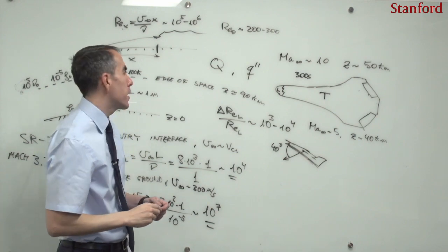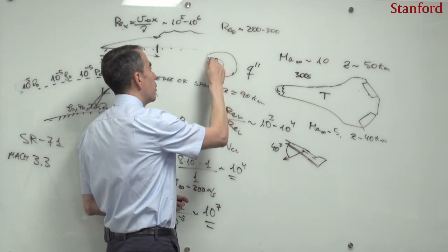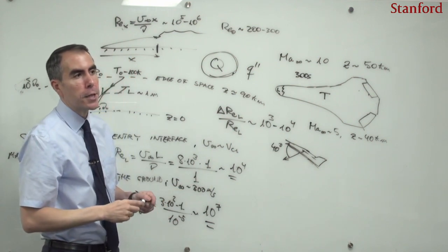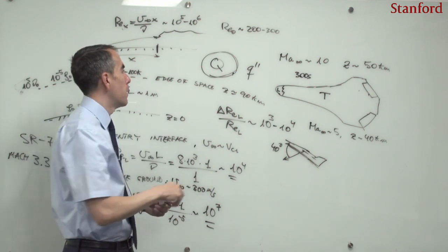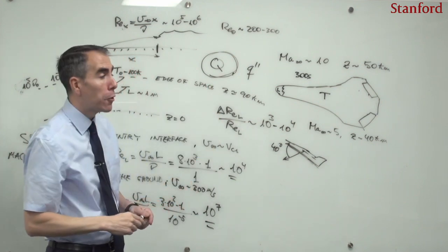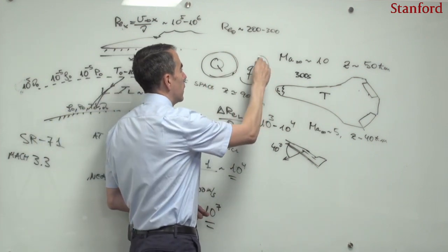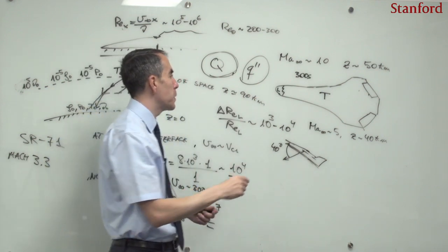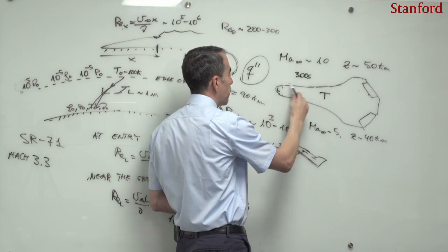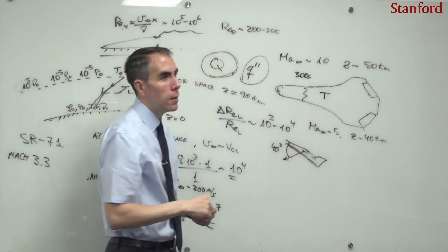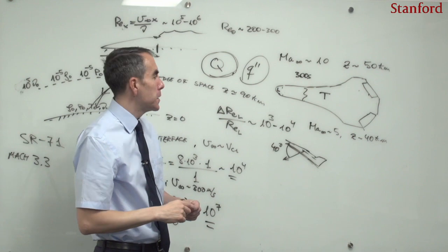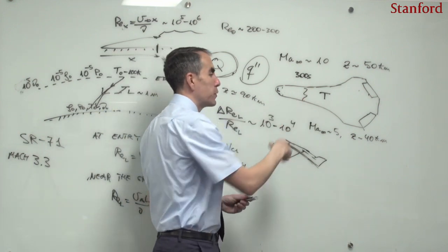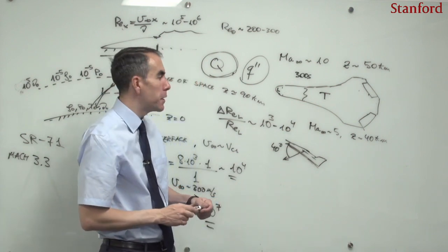So boundary layer transition causes a very small increment in the total amount of heat that the spacecraft was absorbing. But on the other hand, it would cause a large amount of local heat flux. And it is because across the front of transition, there is a large increase in the heat flux. It could be by a factor of 10, as I showed you in the last lecture with the reentry F experiments.